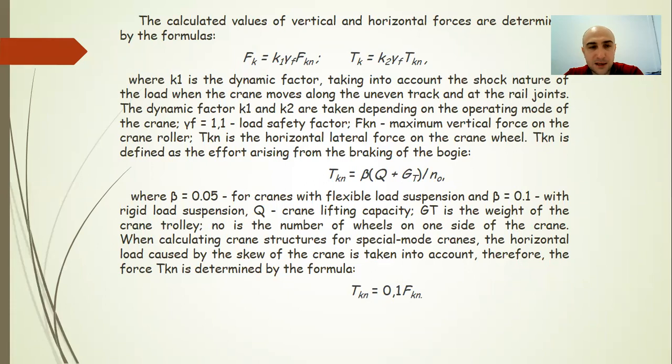Since the fatigue failure occurs as a result of the action not of the maximum but of a repetitive load, when calculating structures for endurance, the most frequently acting loads are taken, which are determined by multiplying the standard loads by a reduction factor depending on the operating mode of the crane.